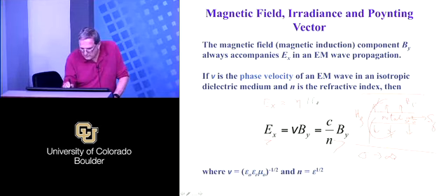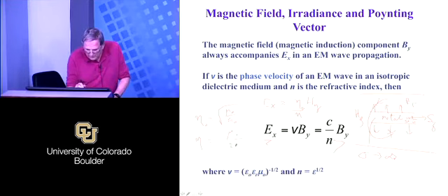and the magnetic field that looks more like this. This eta over here, if you aren't aware, is the impedance of free space. If I'd wanted to put an n in, it would be eta 0 by n, or we sometimes write eta, the impedance of a medium, as square root of mu over epsilon, that is mu r mu 0 over epsilon r epsilon 0.